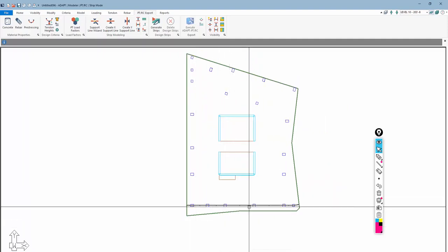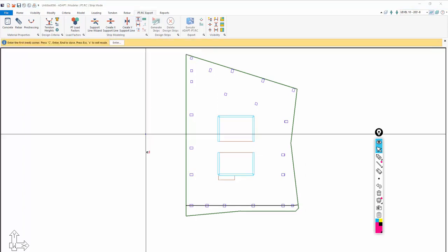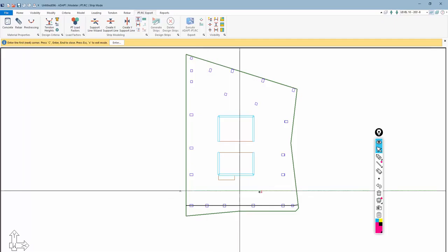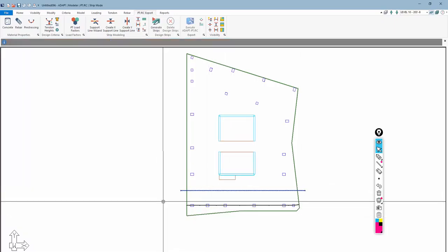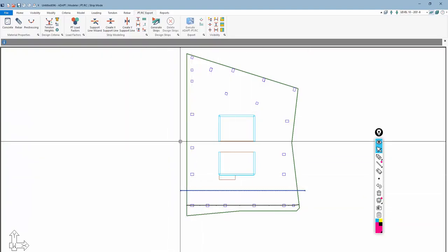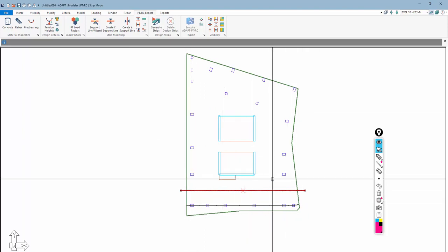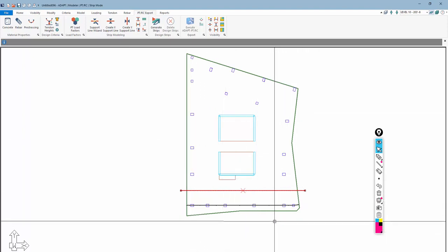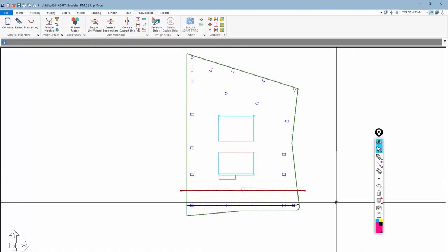Because I'm only creating one strip, I'm going to use what's called a splitter. So here under strip modeling, we'll take this and create a boundary. This just bounds off the top edge of this tributary for this strip, and that's done. If we have additional support lines in the X direction, we technically do not need this boundary because the program automatically will determine, let's say, the tributary based on the presence of the adjacent support lines.